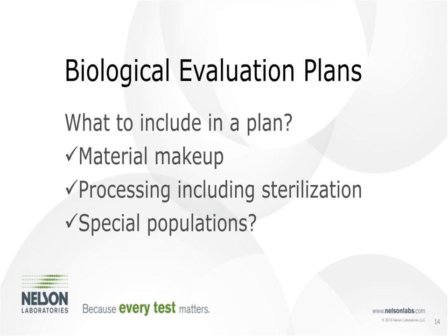That's the next checkpoint. Believe it or not, sterilization can have a huge impact on some materials. What we've seen is EO, ethylene oxide, has a more limited impact. It has heat and humidity that could have an impact in materials and its leachability, but the gas itself doesn't necessarily have as big of an impact as radiation does. Radiation, especially to polymers, can have a huge impact.